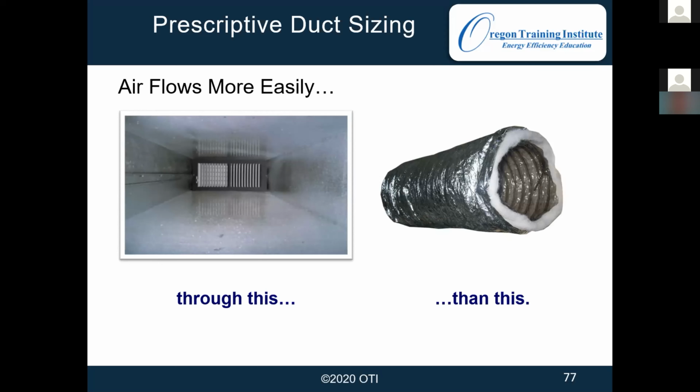And that's going to start with the fact that a hard, smooth duct is going to have less resistance than a flexible, corrugated pipe or duct that has all these speed bumps. So it's going to have more resistance and a lower flow. So hard duct is definitely the preferred method, and depending on the circumstance, usually is mandatory too.